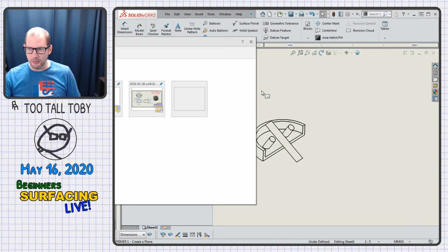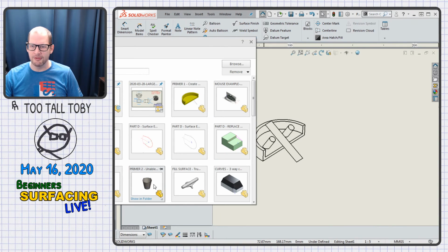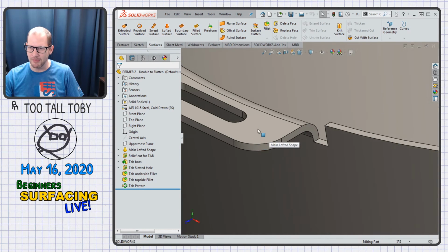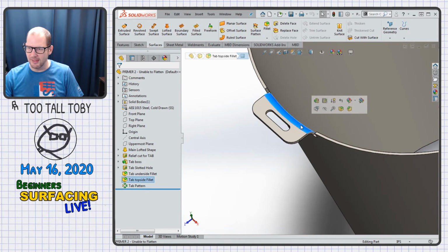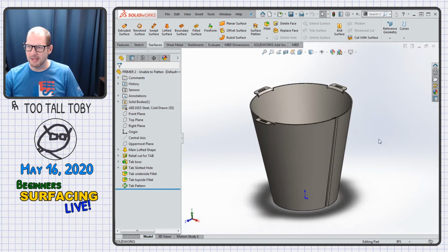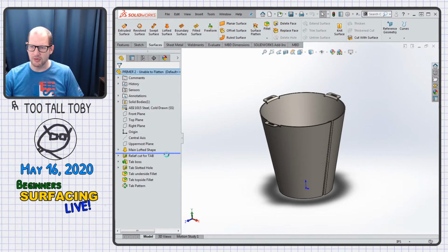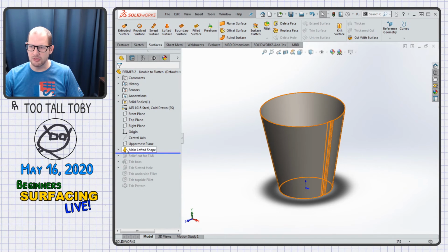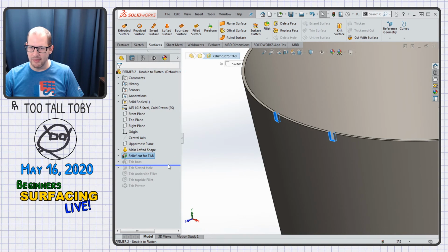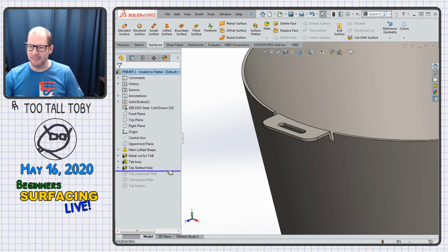And ultimately the reason why is because of trying to create a flange on a curve. When we're in sheet metal, it's often problematic to create a flange like this that's on a curved edge. But we can do it in SolidWorks pretty easily. You can see here that we could create a lofted shape, so just two sketches lofted together. We could create some cut relief for one of these tabs, a little bit of cut relief there. And then we can create just a boss extrusion with the same wall thickness, maybe a little slot there for that hole.